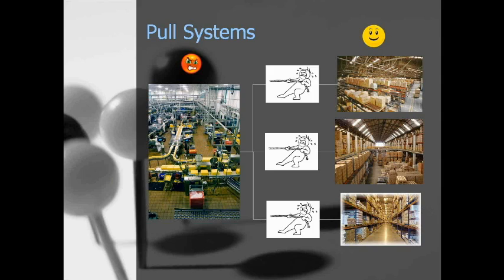Now, you could have the same product being stored at 3 geographically separated distribution facilities, and in a pull system, there is no coordination between those distribution facilities about the quantity they are pulling of that item or when they're pulling it. So what happens is the orders, when they get to the factory floor, come in unexpectedly, cause manufacturing to have to stop running something to do a quick run of this particular product, and it really messes up the ability of manufacturing to produce the product efficiently in a stable manufacturing environment.